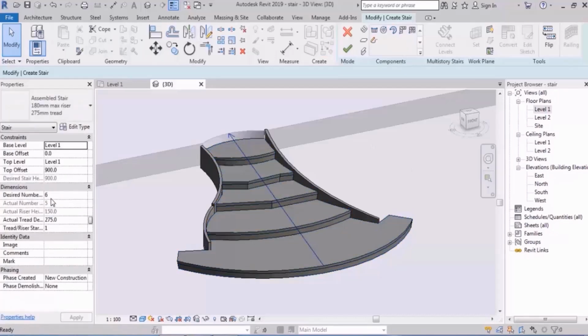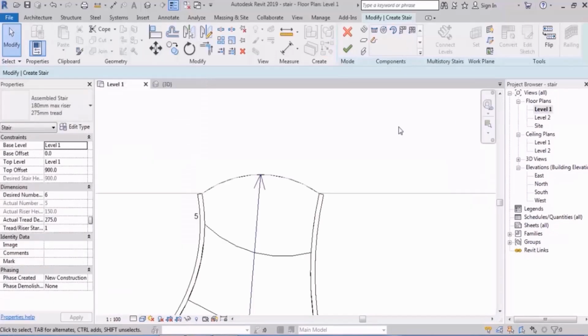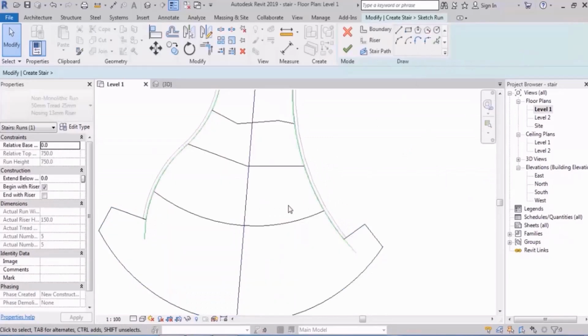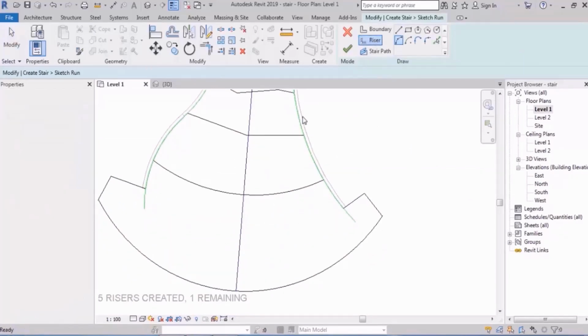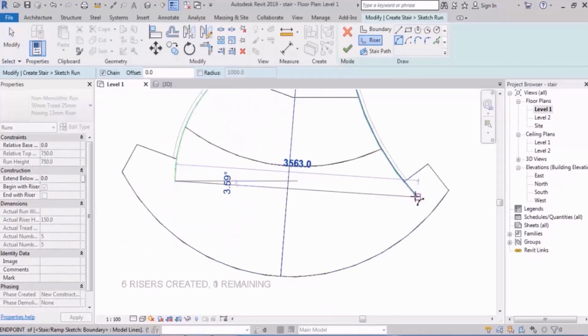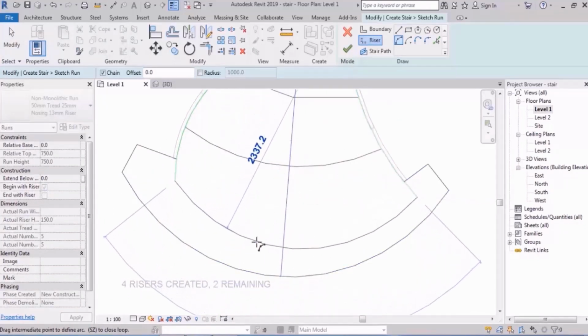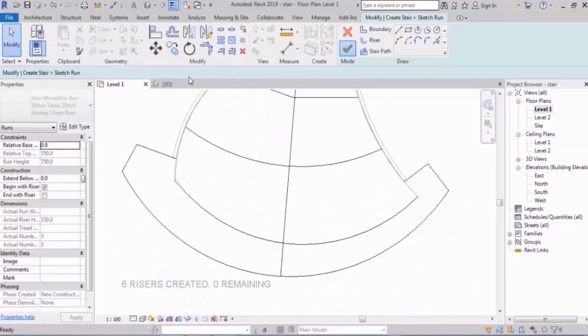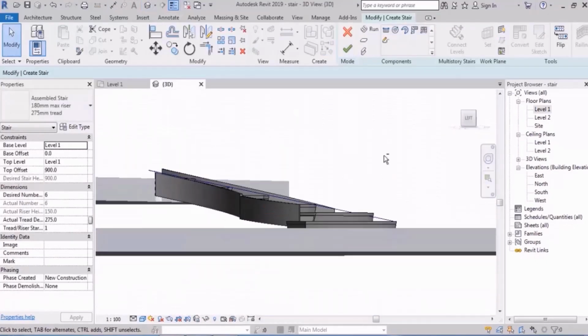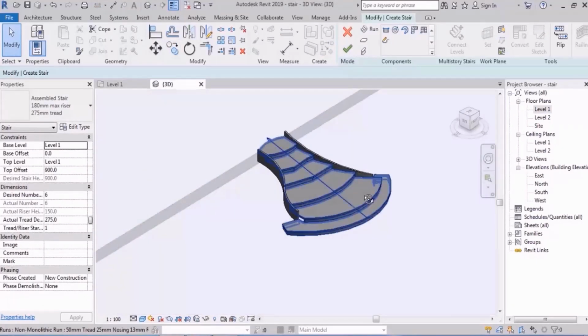Now what's happened? That's right, we need one more riser, so I add one. I click on edit, riser, and it's not actually different where to add it, I add it here. Just like this, and finish. You see that? Now it's a very good and logical staircase.